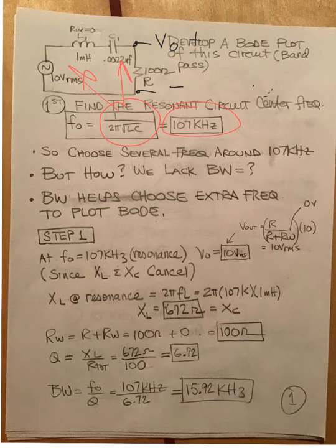Part 1 is the calculations. Part 2, we'll actually sit down and do the drawings so that we can see how to do one. To detect where the minus 3 dB points are, it sure would be nice to know where the bandwidth is on this circuit. That'll help us pick the minus 3 dB points, the 0.707 points. And our first step in the process is shown below.